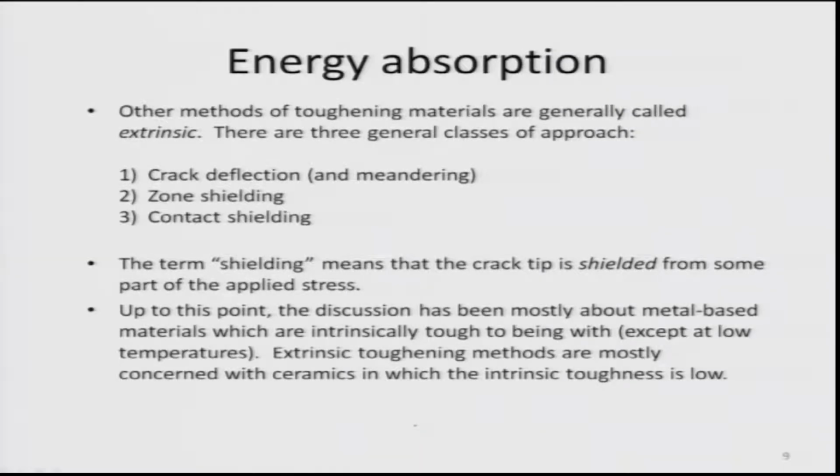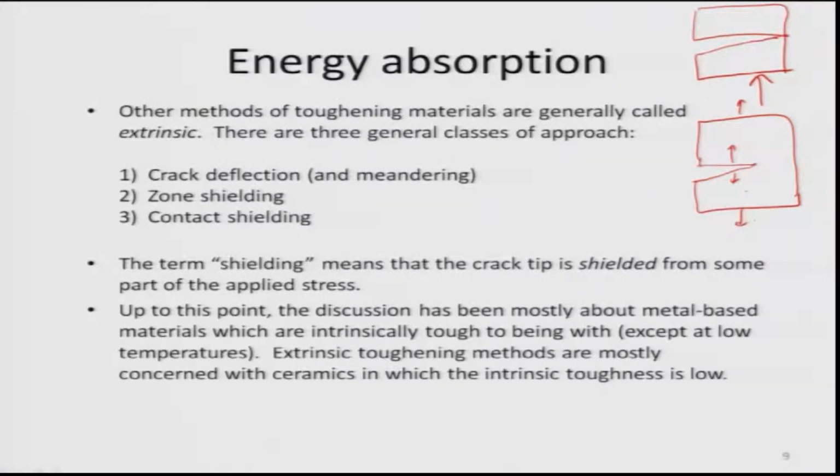Remember, if I have a crack in the material like this, and I want to make the material break, what should I do? I should make the crack propagate through the material. Then it will break completely. So the crack has to open up. If you apply tensile stress like that, the crack opens and then spreads through the material. So in general, shielding means the crack tip, which is going to open up and move, is shielded from the applied stress.